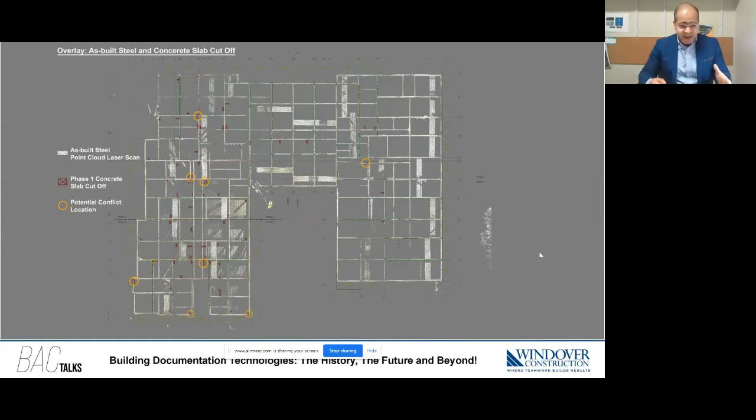What you see here in red boxes is where the factory was planning on putting those vertical MEP shafts to take all the pipes, all the plumbing coming from all the floors, from the steel up. And what you see here in yellow is the clashes we detected through our constant laser scan. So every time we erect steel in different phases, say that part erected first.